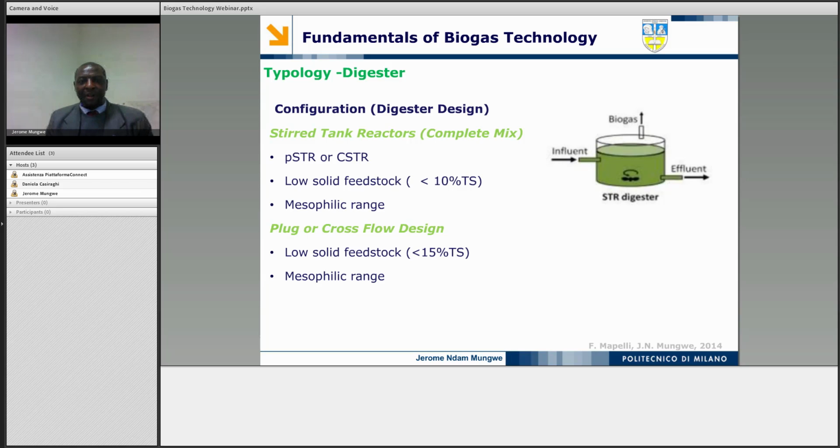Then we can have the plug flow or cross flow design, wherein the feedstock that comes in pushes out the content of the digester without mixing completely. It simply has an interface between the incoming feedstock and the outgoing feedstock. So the incoming feedstock does not mix with what was already inside the digester. Such designs also can function at a slightly higher total solid